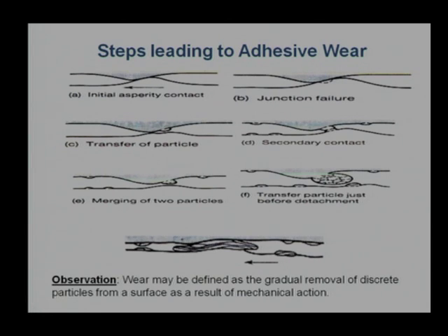One wear mechanism we know, corrosion wear, is basically chemical in nature, but again the wear occurs, the loss of material will occur because of mechanical action. Generation of a layer which is loose or has lesser strength, which can be easily fragmented, is possible through chemical action, but removal of that layer from the surface is only possible through mechanical action. It will not be like a corrosive layer which comes off on its own. It needs to be torn away, it needs some mechanical work on it.